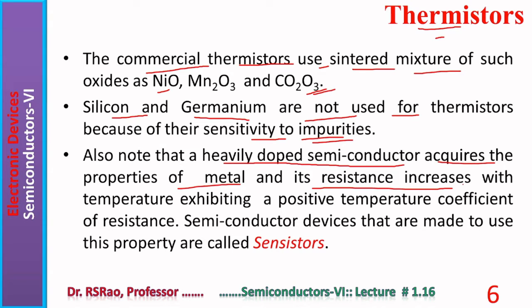When doping is normal, semiconductor's resistance decreases with increase in temperature because conductivity increases with the temperature. But when doping is heavy, then resistance increases with temperature, exhibiting a positive temperature coefficient of resistance. Semiconductor devices that are made to use this property are called sensistors.